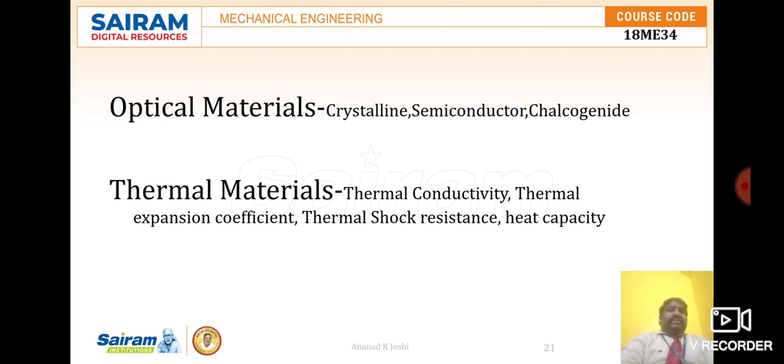For the semiconductors, the polycrystalline forms of these semiconductors could be fabricated into windows, prisms, lenses, and domes by casting, grinding, and polishing of the product. So compound semiconductors such as gallium arsenide, ternary compounds such as gallium aluminum arsenide, and even quaternary compounds such as indium gallium arsenide phosphide now serve as lasers, light emitting diodes, and photodetectors. So this is all about semiconductors.